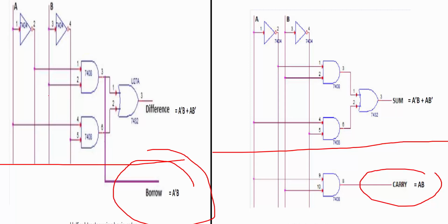Okay, so before implementing all this circuit, always practice to write the IC number properly in this diagram and mark this input output port connectivities. For that, we need to refer that IC pin diagram.